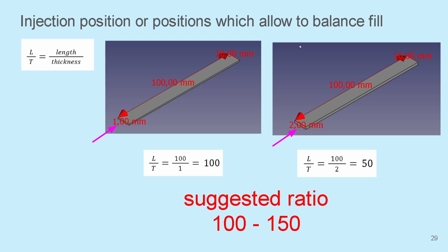The primary task for the injection point is filling the nest. This is not so surprising, of course. Plastic material has shrinkage. After the filling phase, shrinkage causes a smaller part and finally warpage. The injection point in this stage allows adding material and minimizing part warpage. This is possible when the injection point is in a good position.